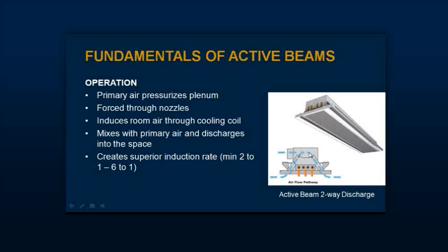One key note, though, that when I normally give a recommendation, if I'm cooling with water systems, the water, either hot or cold, is simply to handle as much of the sensible or dry load in the occupied space as possible, and then I would try to do all humidity control or latent energy removal with the volume of supply air I have inside the space. And the idea behind this is that I minimize my risk of condensate if I'm using this for cooling, which is a common concern. And also I've optimized my building's energy consumption in terms of how much it takes to transfer the amount of cooling or heating to the space, water being the more efficient media.